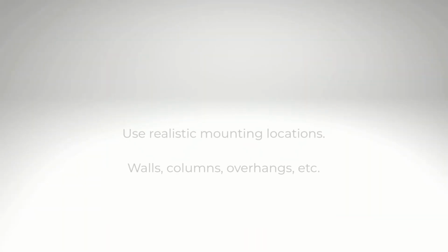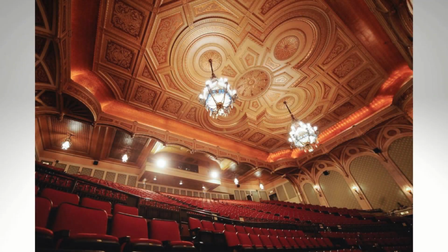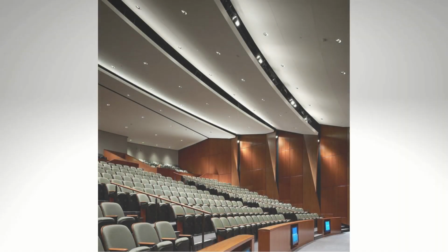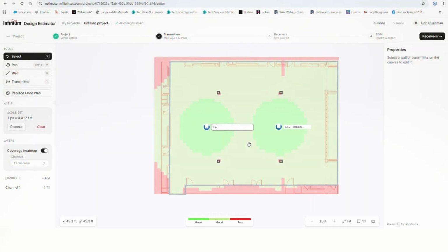While doing this, make sure the placement is realistic, meaning that a transmitter could physically be mounted where it's positioned on the drawing. For example, in a multi-level theater, the ceiling may not be available as a mounting location because of acoustical treatments or because it would disturb the finished look. Since this is for estimating purposes only, the coverage will be close enough. To rename a transmitter, double-click on it and enter the name.